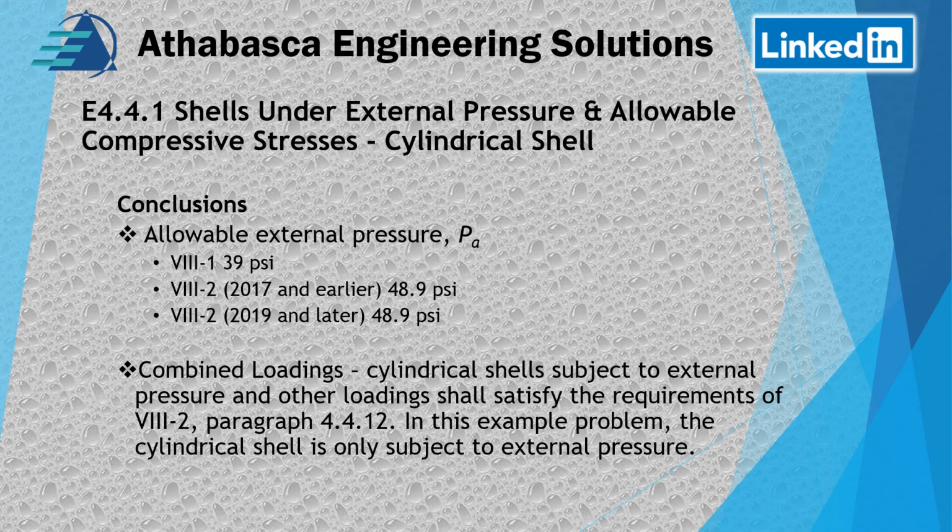Now, I want to have a note about the combined loading. For cylindrical shells subjected to external pressure and other loadings, you need to satisfy the requirements of 4.4.12. Have a look at this. In this example problem, the cylindrical shell is only subject to external pressure. So if you have internal pressure and external pressure, and then there are cyclic loading effects, this can get pretty complicated pretty quickly.